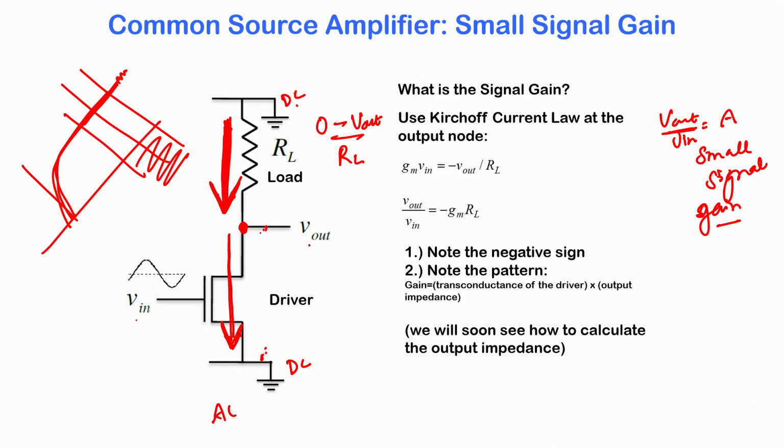But on the other hand, you have a gate voltage fluctuation V in. What is important is to see whether there is a gate to source voltage fluctuation. Is there a fluctuation in either Vg or Vs? Vs is not fluctuating because it is DC, but the gate is definitely fluctuating. The fluctuation is basically V in, and therefore yes, there will be a current through the MOSFET, and the current, as we looked at, will be given as Gm times V in, where Gm is the transconductance.